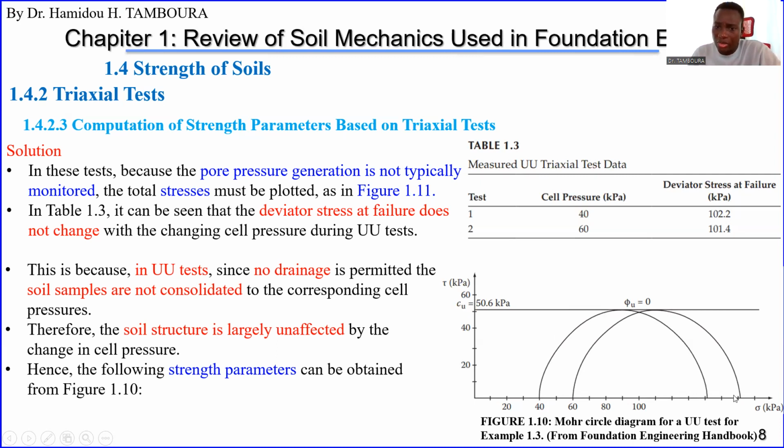And the cohesion is just the value where this line crosses the vertical axis. That makes the cohesion here 50.6 kPa.